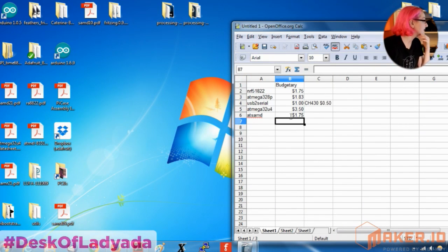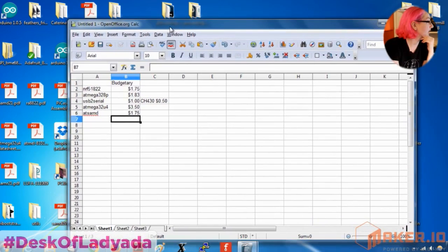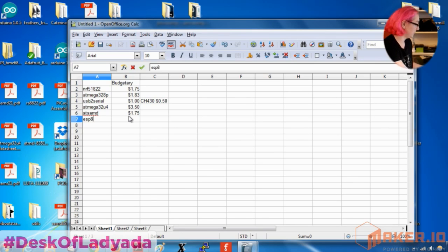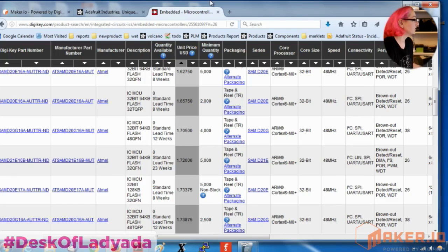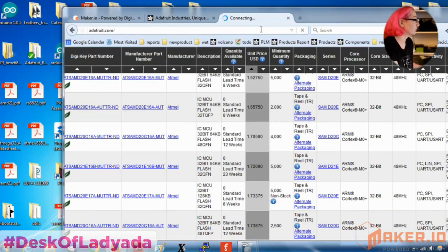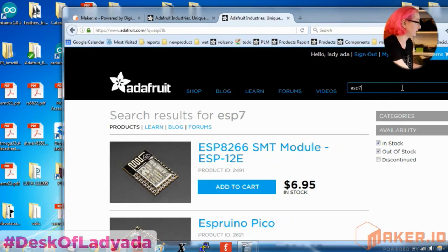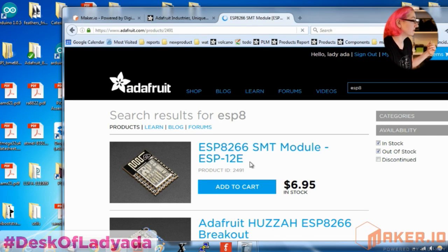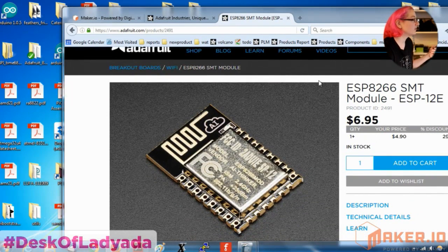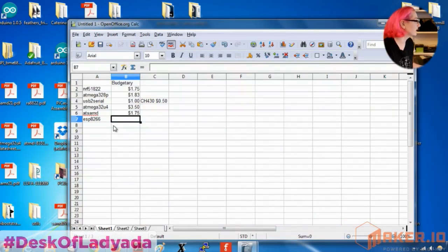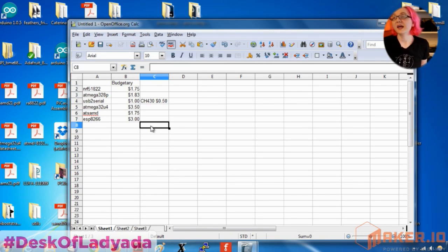We had multiple brunches where we talked about which chipset to go with. I actually ended up also adding ESP8266 as a possible core. That is a module that we have available, and you buy these direct from Espressif. We get these modules, I think, for about $3. The problem is you also need one of these USB to serial converters, so it ends up being about $4. But you get Wi-Fi. I was actually thinking about Wi-Fi, and I'll tell you why I ended up not going with Wi-Fi, because I had to make a quick decision.